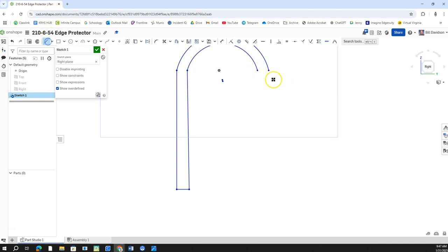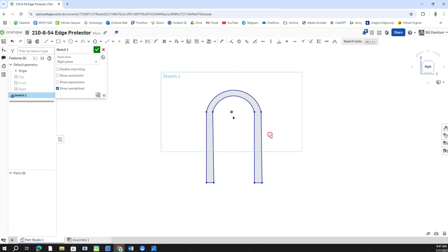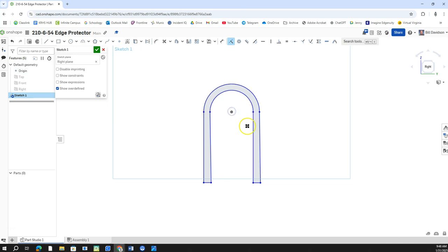I'm sorry. Come down here, straight down here, come over here a little bit, and back in this way. All right, I'm gonna go ahead and do tangent constraint. I want them to be tangent. Undo that real quick because I want to make sure that they're concentric first. So they're concentric, and I'm actually going to do this where I say that this goes right on my origin point. Nope, not a dimension. Coincident, I clicked the wrong thing, went too fast.